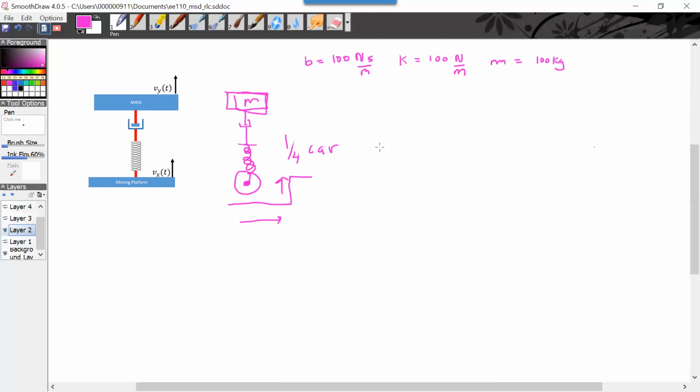So first rule, the mass becomes a capacitor. One end we just tie to ground. That's just what you do right off the bat. Then we have a damper connected to the mass. Now, if I have a capacitor and I connect that to ground, and then I connect the resistor, that end of the resistor is tied to ground. So you never do that. You always tie these components to the other side.